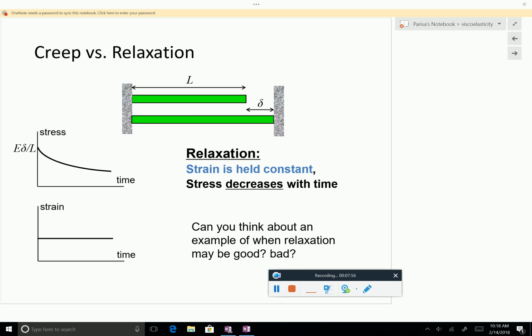I know this may not be very clear to you if you don't know really what this is about, but it could be a very bad thing in pre-stressed concrete members. I don't know if what I explained made sense to you. So you have some sort of large bars. Imagine large steel reinforcement. You put it in tension, you pull on it, and then you pour concrete over. And then you cut the ends, so the concrete starts with being under compression. Does it make sense? And people do that because concrete is generally very weak in tension.